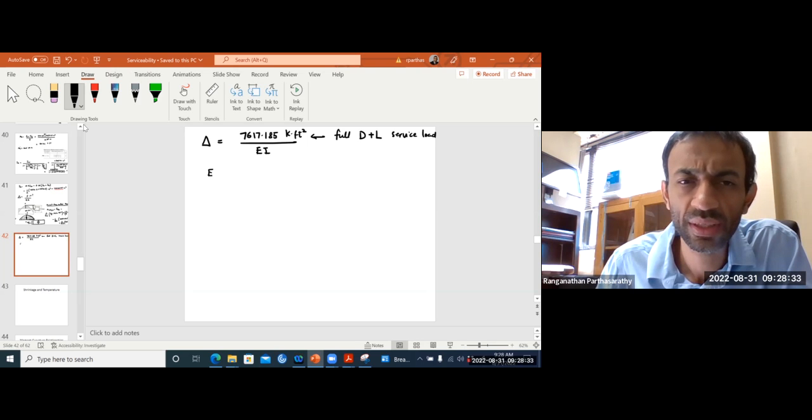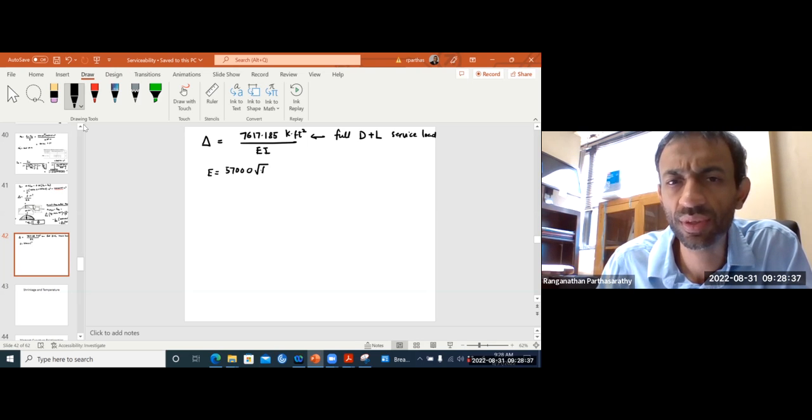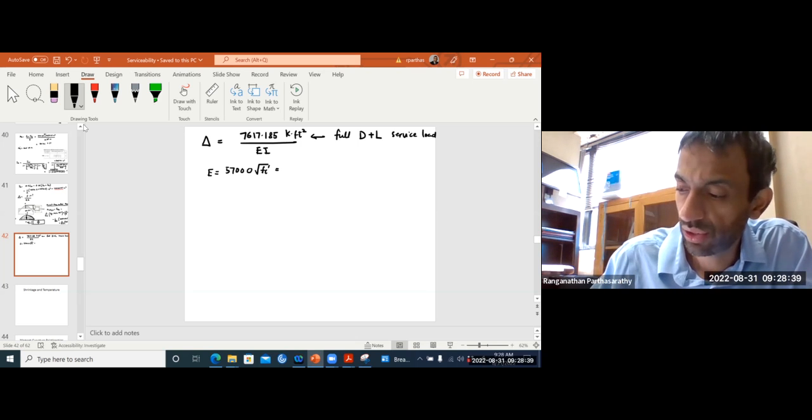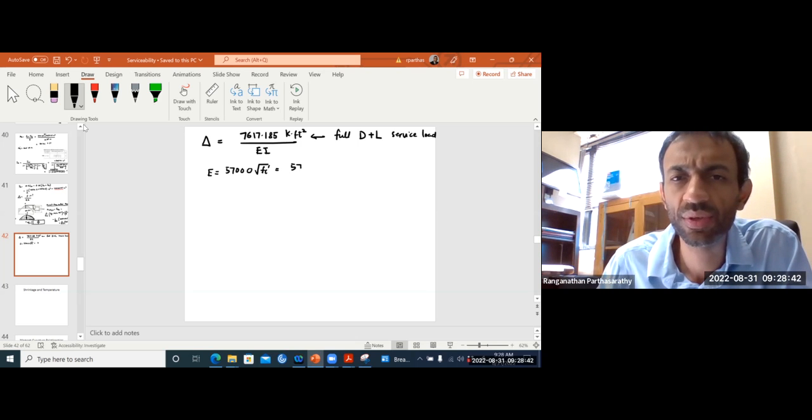So what is E? E is 57,000 square root of FC prime. That's your elastic modulus, if you remember from the code.